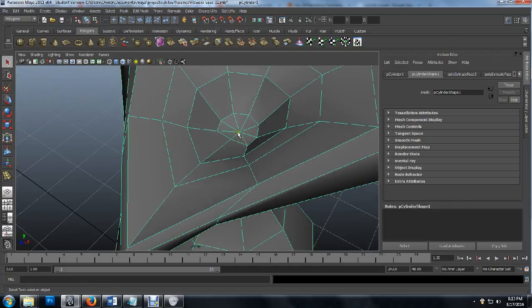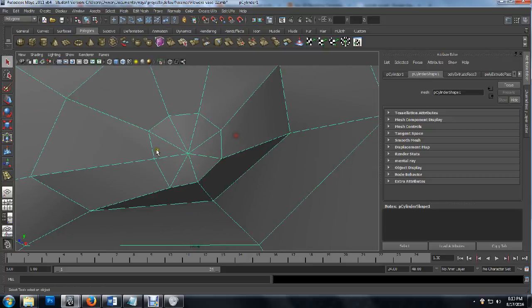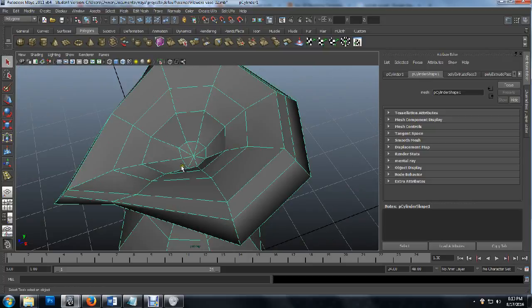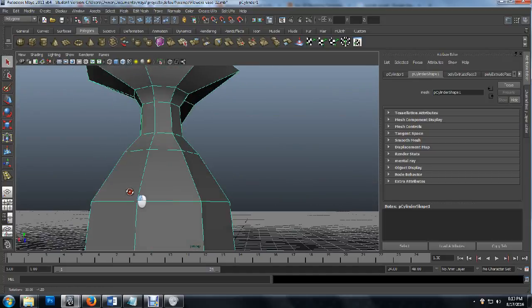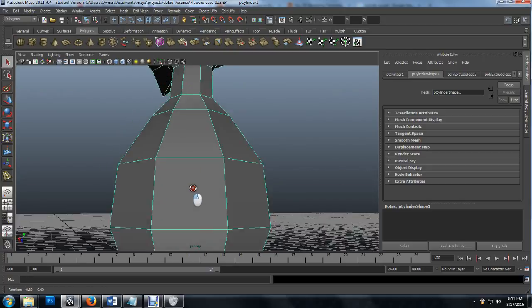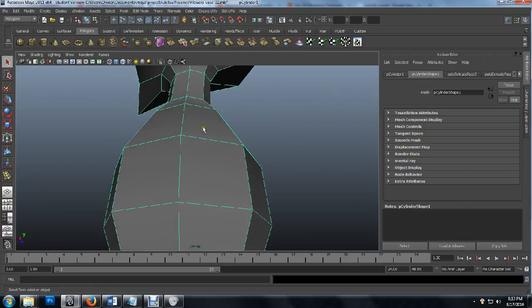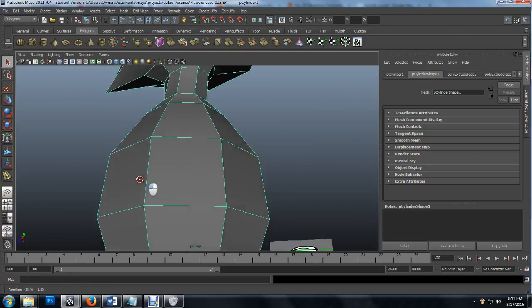So it's always best to avoid doing triangles or n-gons. That's like a hexagon or a pentagon or an octagon. Try to avoid those with 5 points or 8 points or whatever, because it's just bad geometry. You don't want to really mess with that. And then when you come back and you want to modify this in some fashion, it's easier to do it if it's a quad than if it's all wonky and hunky-dory.